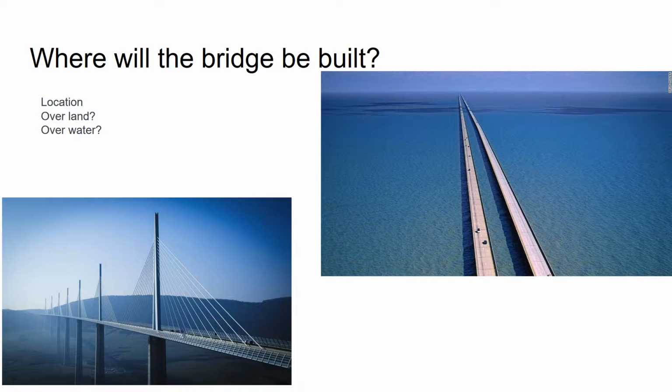So where the bridge will be built, a couple things you have to consider. It's either going to be built over water or over land. If it's built over water, there's a lot of considerations you have to take into account, like how you're actually going to get the bridge pieces out on the water. There's a lot of extra equipment you have to use, like boating cranes. A big crane on a boat is what that is, or you'll have to use boats in general just to get your materials out to the end of the bridge, or wherever you're at in that bridge construction process.